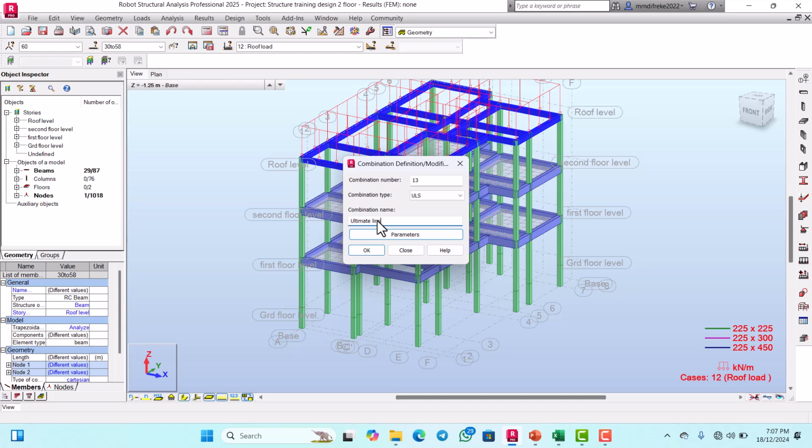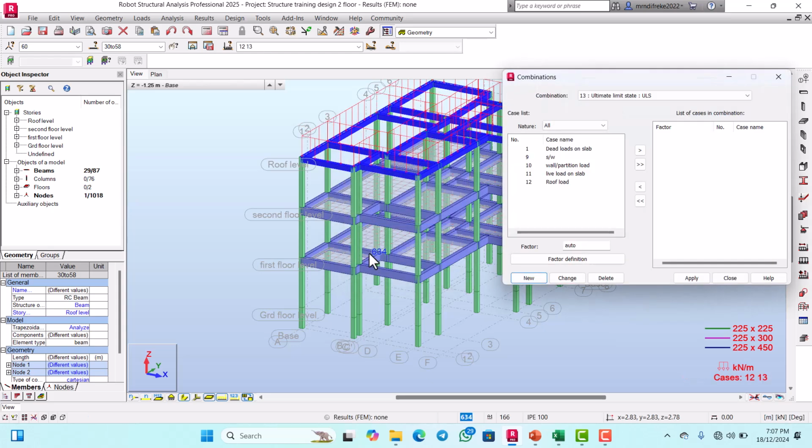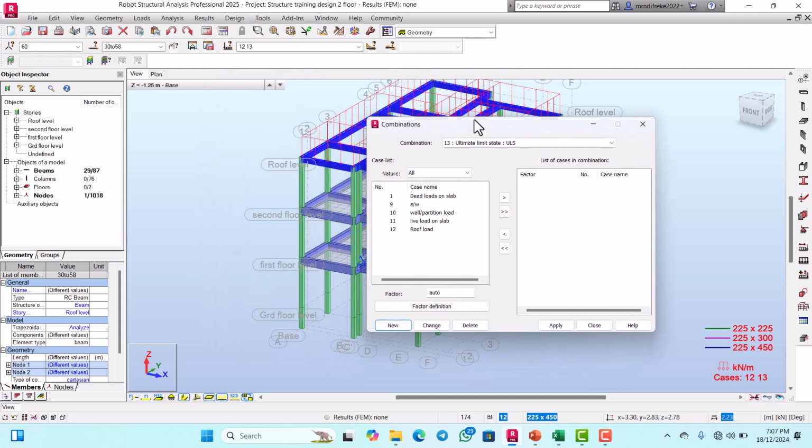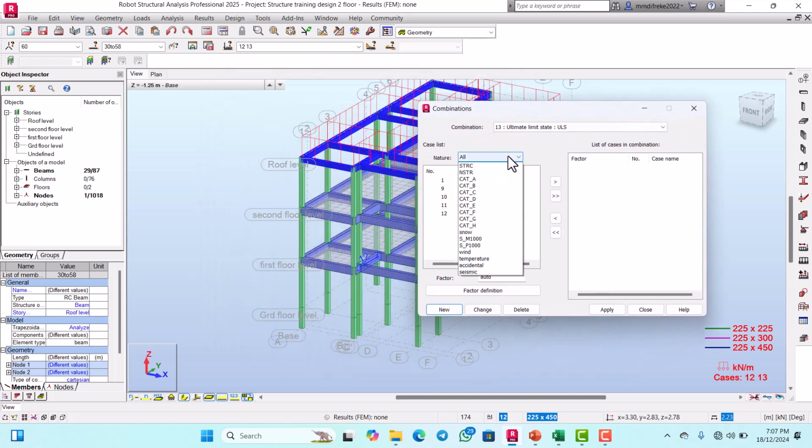So under ultimate limit state, you can now define your ultimate limit state. Okay, so you click on OK. So when you click on OK, you come to where you have structure. Under structure, you are going to have all the list of your dead load on it. So you now see that the factor for dead load is 1.335. So you click here to move everything inside. So meaning that this will be multiplied by each of these load definition.